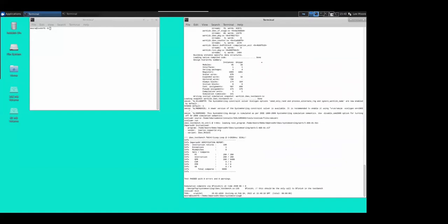So here's the interesting part. There's not a lot to show because, of course, this is working perfectly fine. In fact, all that happens when we execute that program is that we get a summary telling us that we've performed a number of assignments or sets, which is where the client watching the RVVI interface has controlled the API to set information in the Imperas DV environment, and then it's done a number of comparisons. So here we see on the PC 200 sets, 200 compares. The instruction bit pattern, when we perform a fetch, we've got 200 sets, 200 compares, and on the GPRs, we have 200 sets and 6,400 comparisons.